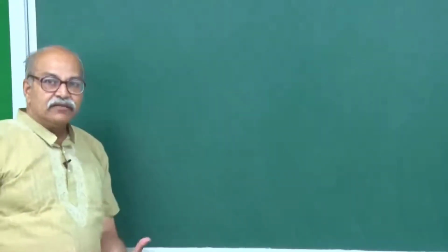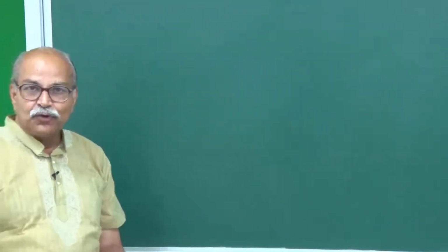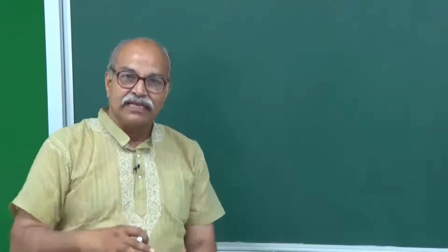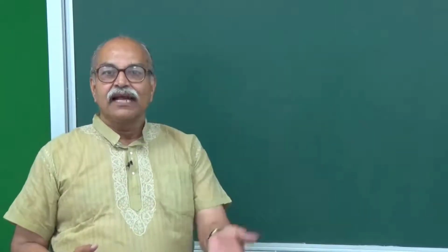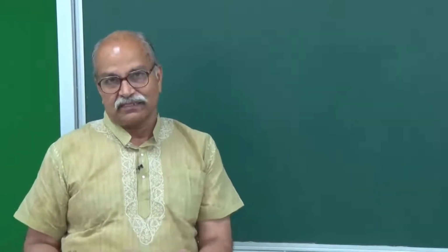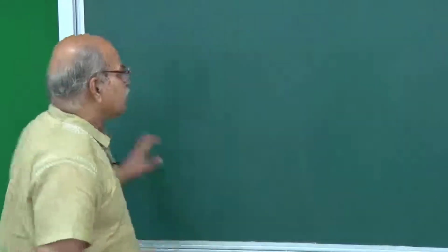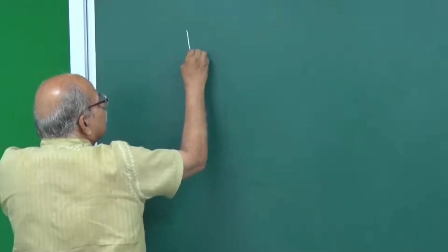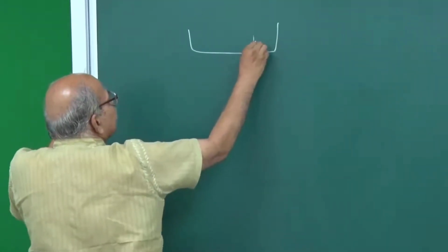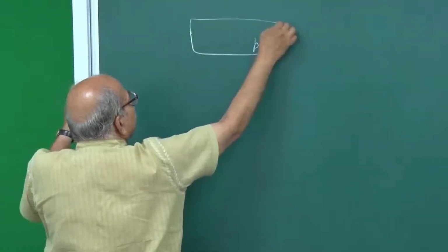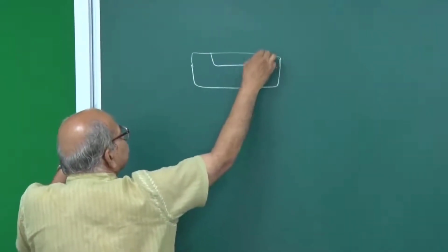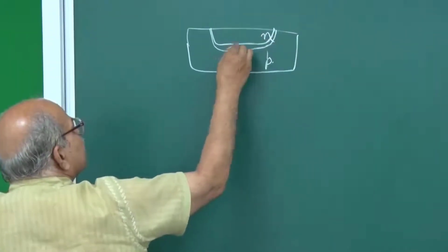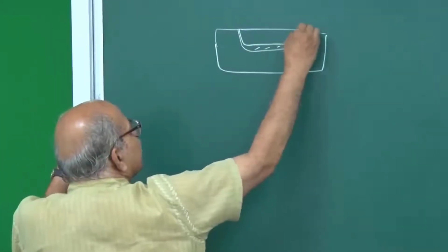In a solar cell, like the photodiodes we talked about, light falls on this PN junction, and that light creates electron hole pairs. Essentially it is the same mechanism, but the construction is slightly different. You take some P type first, and then you diffuse N type on it and make a depletion layer, so that you have this PN junction, and this is transparent.